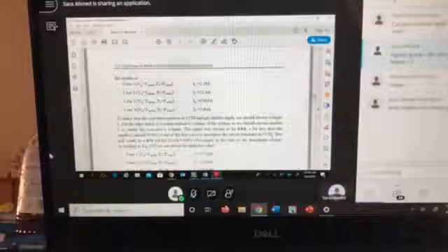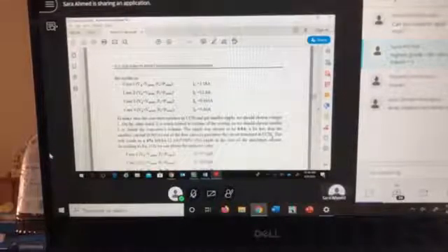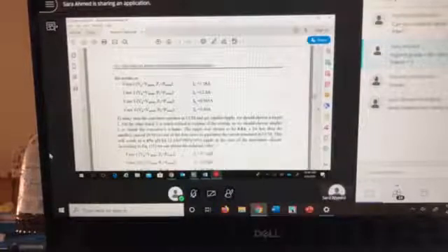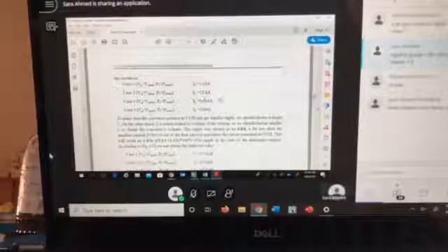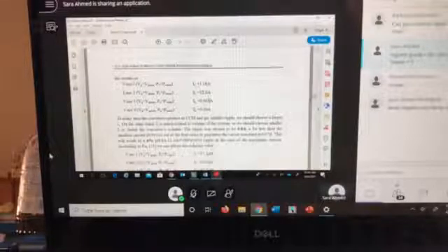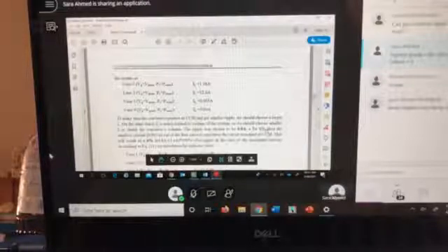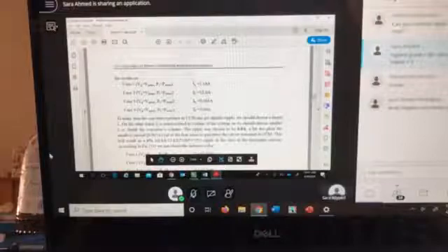So usually in the book, it tells you choose the ripple to be about 10 to 15%. Yes, that's correct. But since we are doing it for all the operations, I need to make sure that it is smaller than all the currents, smaller than the smallest current. And that basically guarantees that I stay in CCM, and that's what the project requires me to do.